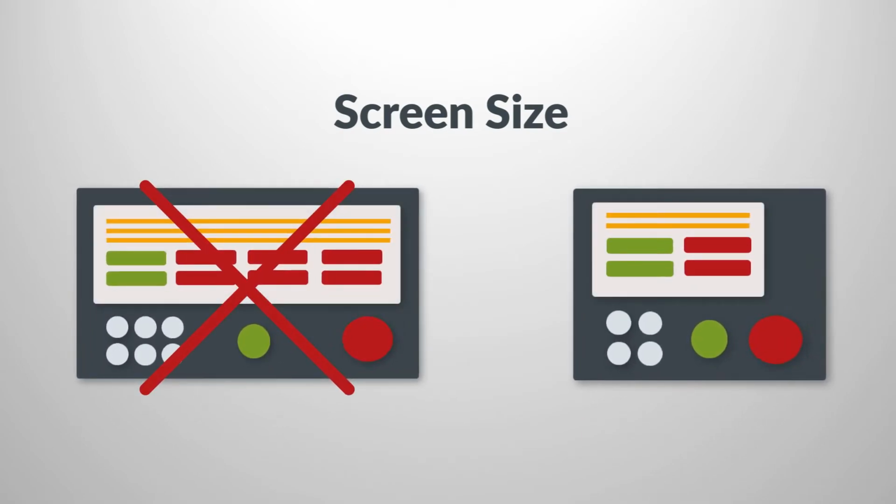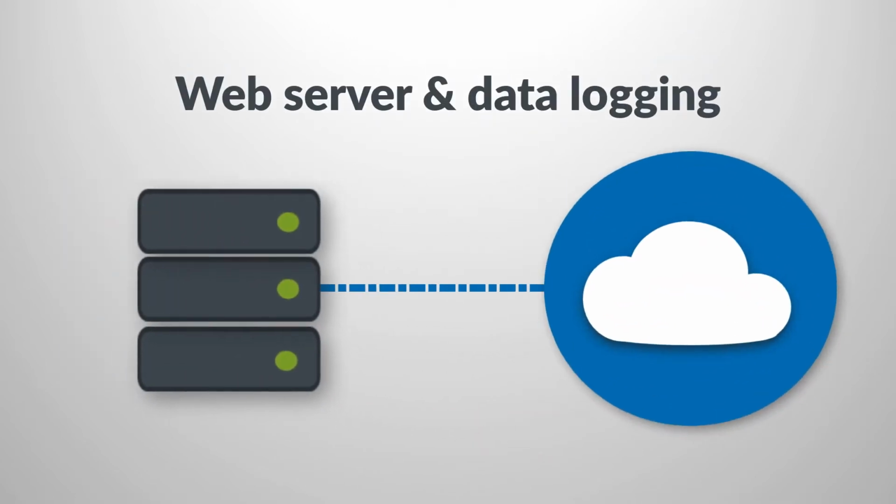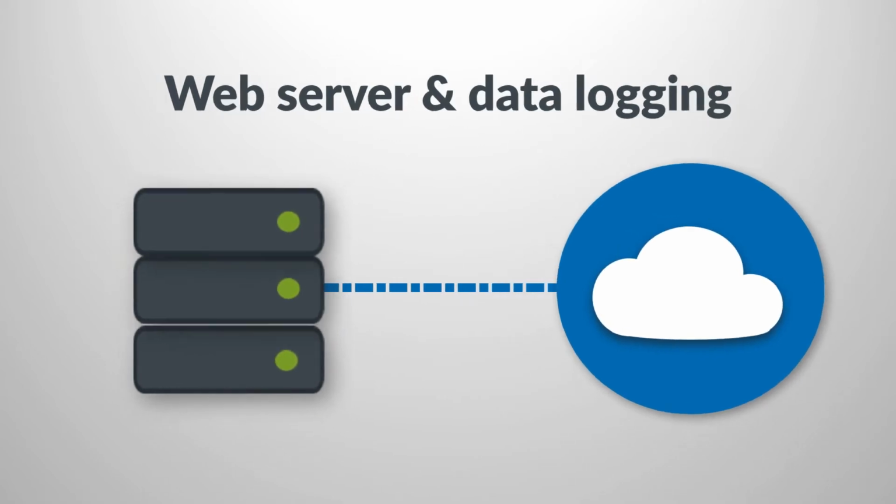It doesn't pay to get a larger display or to spend time on fancy graphics. While the OIT may have limited protocol availability and features, it may still provide a built-in web server enabling remote access to some of the data and may even have data logging, but limited memory to do so.